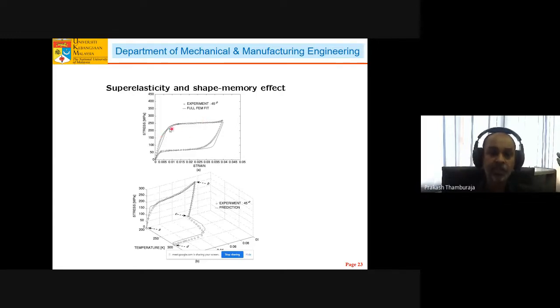As you have phase transformation, you have a release of latent heat as well. When you have reverse loading, you get a reverse transformation from martensite to austenite phase, and the latent heat is absorbed. So if you touch the sample, it'll be cooler along the reverse loading cycle, and it'll be heated along the forward transformation.